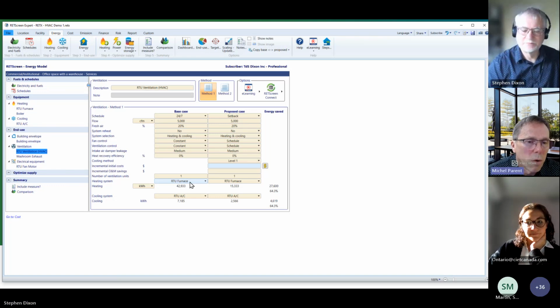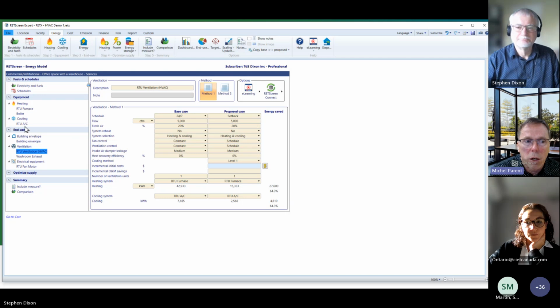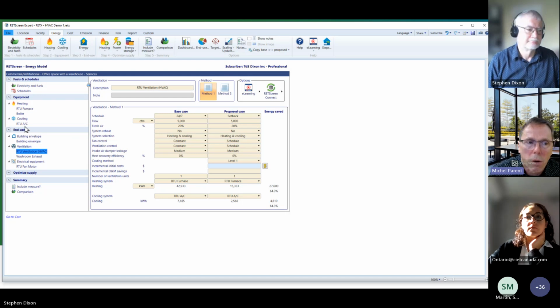So in this example, you have a gas-fired rooftop unit that could be single zone, and that gas-fired rooftop unit would preheat the outside air, but would not provide the space heating, which would come from the boiler. Now, if you had a cold deck system, there's no link between the envelope and the ventilation component, regardless of the system. So you definitely would need to have some form of heating system associated with your building envelope, just like the boiler. And in your ventilation system, you would have a furnace still, but it would be assigned to a VAV schedule rather than a standard hot deck system schedule.